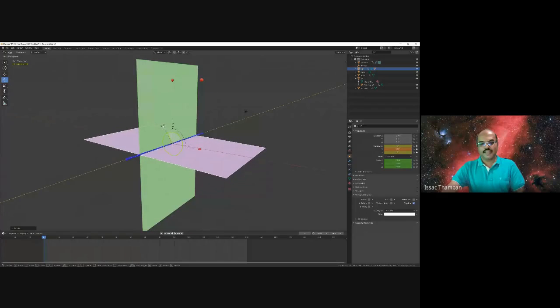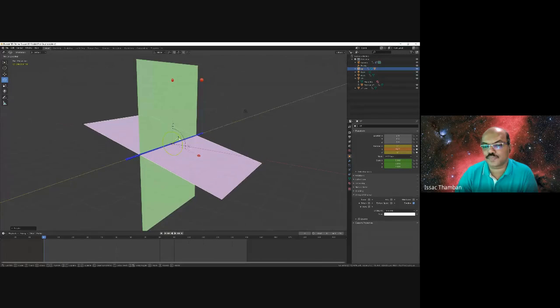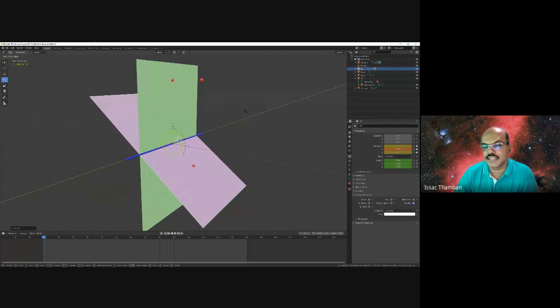Initially, the projections were like this. Initially, it was horizontal. This is the projection obtained over the vertical plane. This is the projection obtained over the horizontal plane. So, for representing the projections over a drawing sheet, what you have to do? You have to tilt the reference plane, that is the horizontal plane, pivoting the XY axis in the clockwise direction.